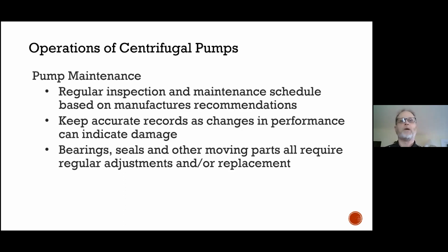Bearings, seals, and other moving parts require adjustments and/or replacement. That would be determined based, again, on the type of bearing. There are sealed bearings, and that always seems to be a question on the exam. How often should a sealed bearing be lubricated or greased? And the answer, of course, is never, because there's no grease nipple. There's no way to do it. There have been famous stories of pump mechanics drilling into a sealed bearing casing and installing their own grease nipples. No, don't do that.